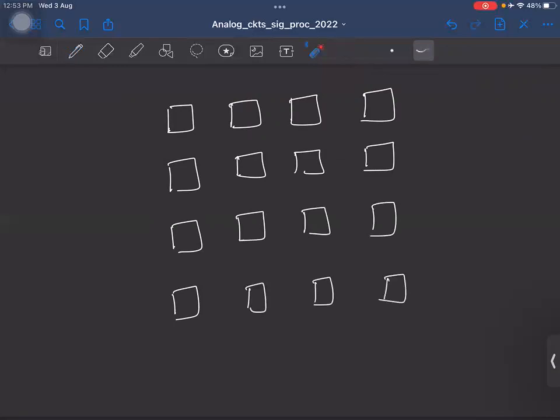You choose some of them as the 10 and have the others as dummy. Basically, they will be additional. They will not be connected to the circuit, but they are just there to make sure that the operating environments for all of them are identical, right?